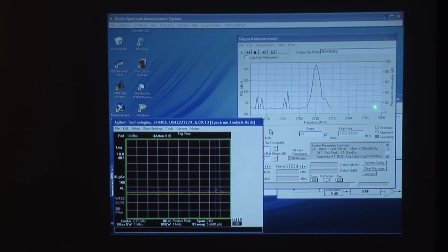We'll go ahead and run this out to 2800. Had this been a radar measurement in a good location and field, the dynamic range that we would have had here would have been at least 100, preferably 110, maybe as much as 120 to 130 dB. Here, as I said, we're only getting about 40 dB of dynamic range because of our measurement location, but our point in this part of the talk is to show how the measurement algorithm itself works.